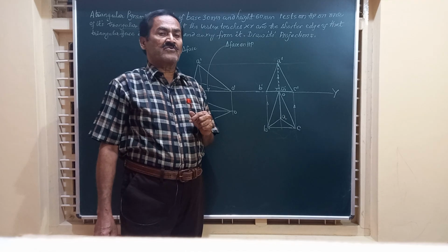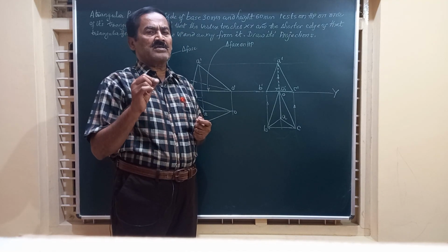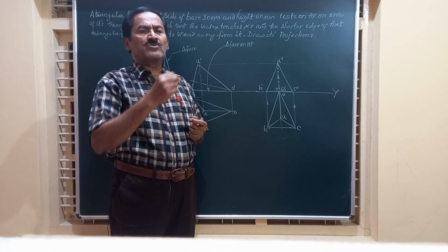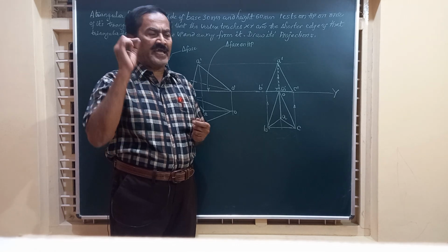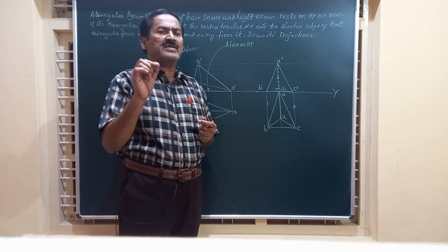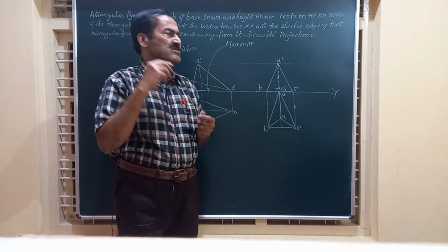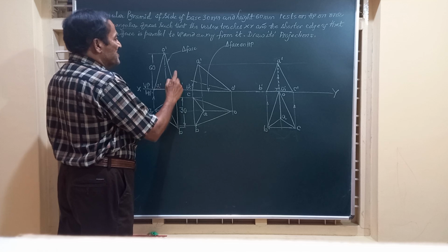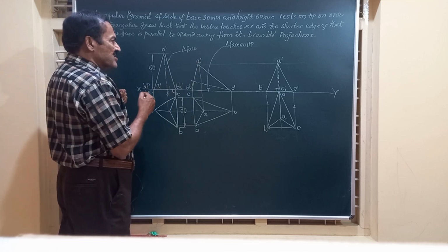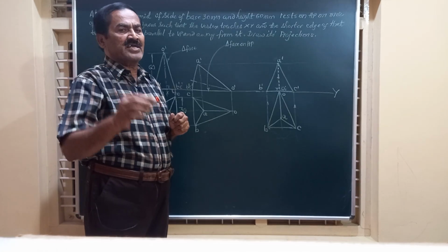And now, friends, you have to just see the front view of the solid and find out which particular edge or line in the front view represents a triangular face. So, to have a triangular face, there should be 3 points on that line. So here, if you observe, O dash, B dash, C dash represents a triangular face, whereas O dash, A dash represents a slant edge.